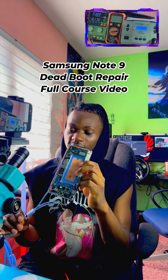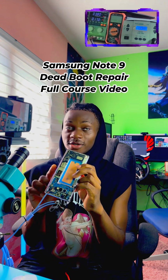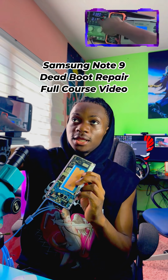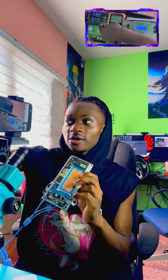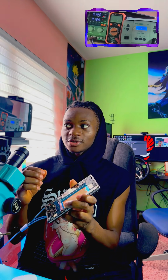We have this Samsung Note 9 with a power problem. If you take a look, it's already connected to my DC power supply, and you will see that we have a current leakage right there. So we're going to talk about that. I've disconnected the cable. I'm going to reconnect it so that you will see that's an auto current leakage, which is abnormal.